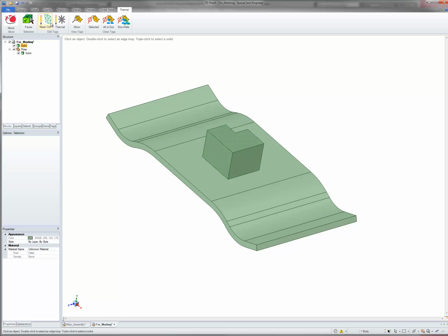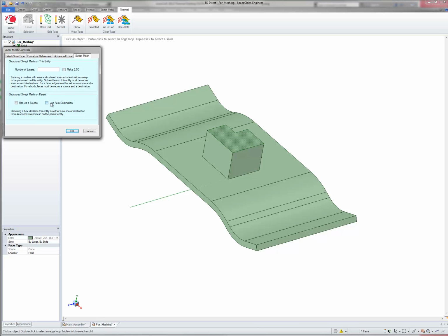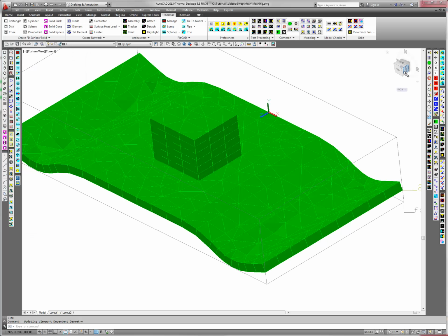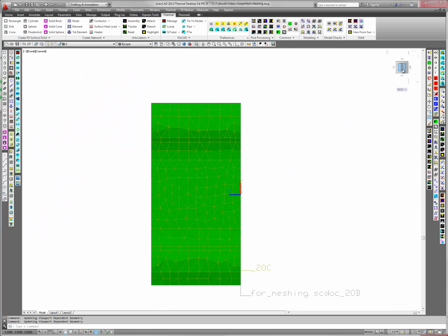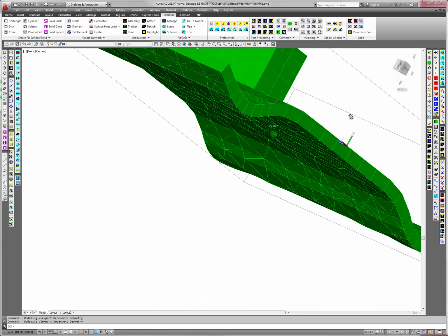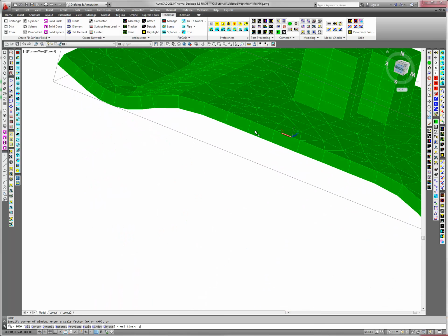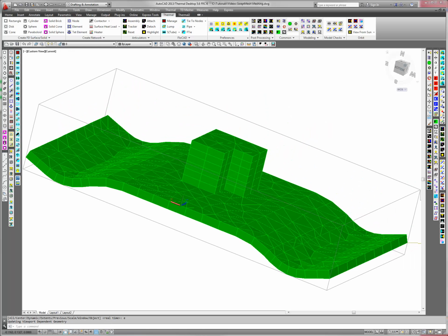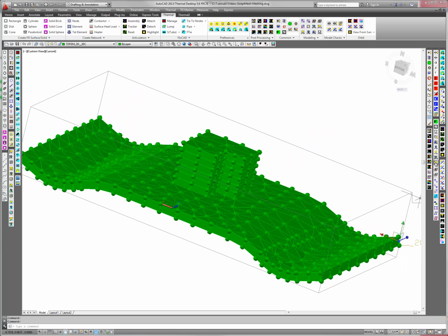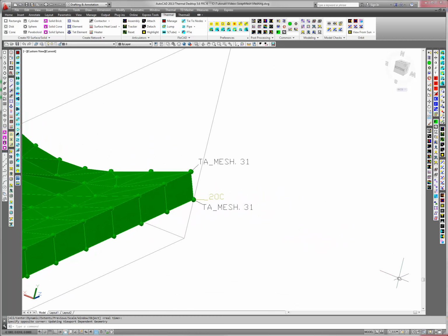The new solid will get 6 layers. The top will be the final destination. Another synchronization will show what I've done. The global mesh control is set to matched, so you can see the imprint of the new component in the mesh of the original component. The new component has 6 layers, implying a significant gradient is expected through that solid. The original thin component is 2.5D, meaning it is a single layer and the node numbers are the same on the top and bottom at a given location.